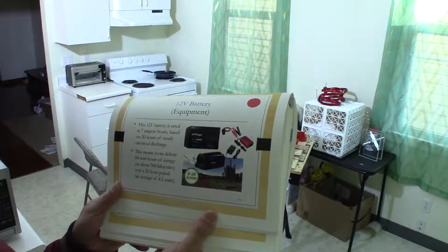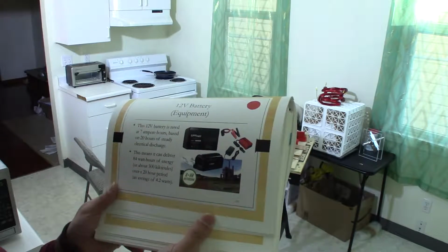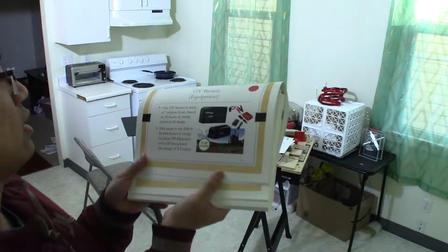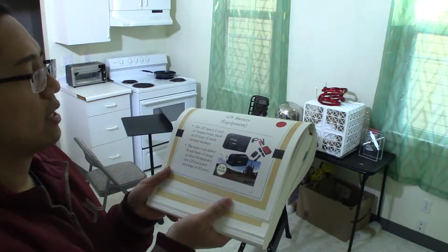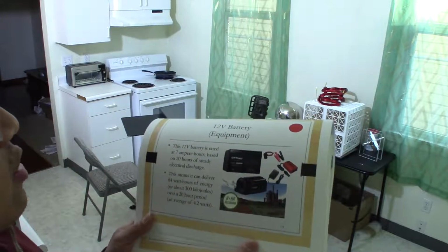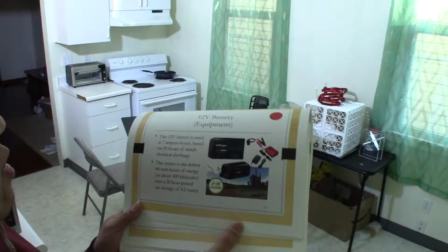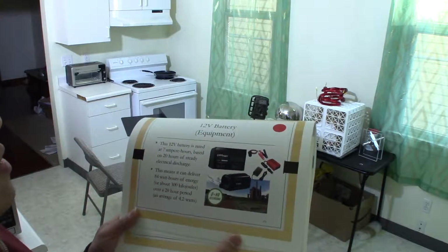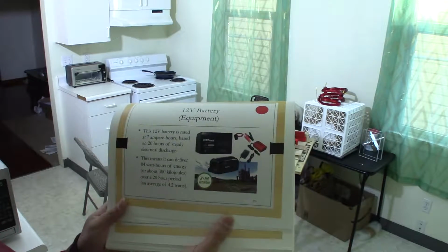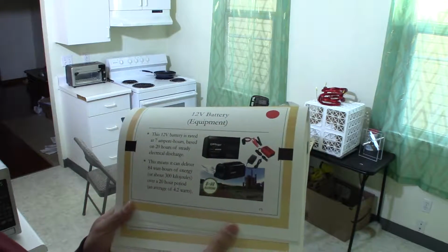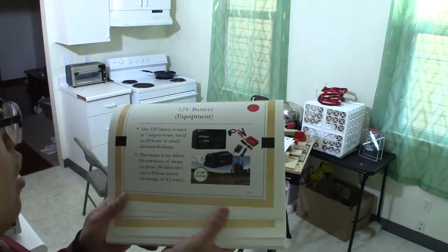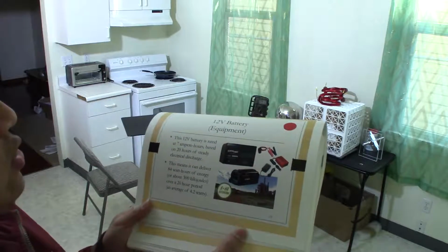Okay, so basically, that's at 4.2 watts. So if we're drawing a little more than twice that amount, okay, so 84 watt hours, that is the result of taking 12 volts and multiplying by 7 ampere hours. That's 70 plus 14 watt hours, or 84 watt hours. Okay? Now we're about 300 kilojoules, and that's over a 20-hour period that it's rated to discharge, so 4.2 watts.